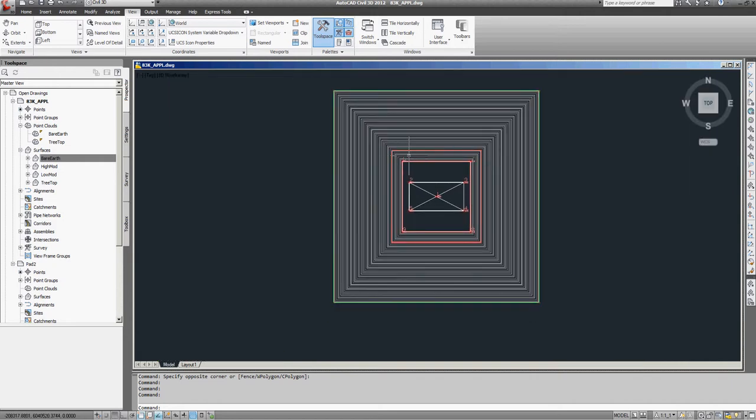What we also see as we go further out is that we model our cuts and fills, and this is best seen in an orbit. We're limiting ourselves to a 3 to 1 slope on our fill section of the lease and a 2 to 1 slope on the cut sections. So what we'd like to do is take this model of a lease, put it beside that Apache lease, and figure out what's the ideal elevation for the well center so as to minimize the difference in cut and fill so that we're not moving dirt around. As well, we have to ensure that the disturbance is limited to the well area.